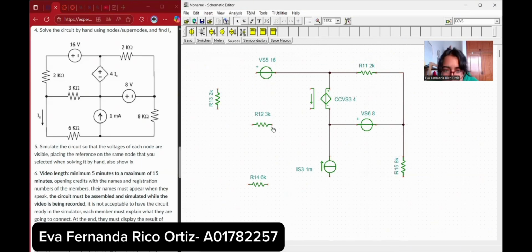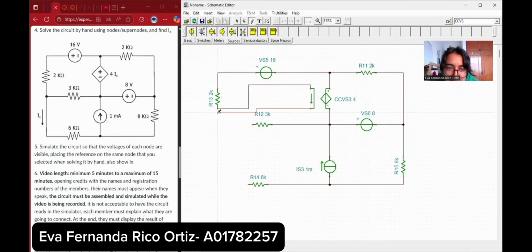In Tina, we need to make sure that our cable connections are really specific because it's a software that's really sensitive towards cable connections. So if you mistakenly connect a component, it's very punishing. So we need to make sure that everything's correct. Now, what I did here, this current will be the one that's flowing through this resistor into this resistor. But I cannot just set this parameter like in here, because being a current, it needs to be, like in real life, connected in series with the one that we're measuring. So we make this connection.